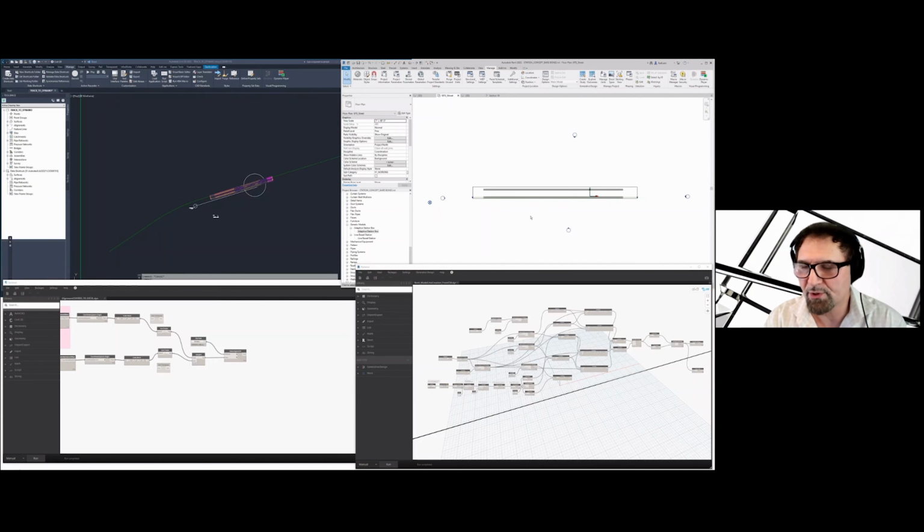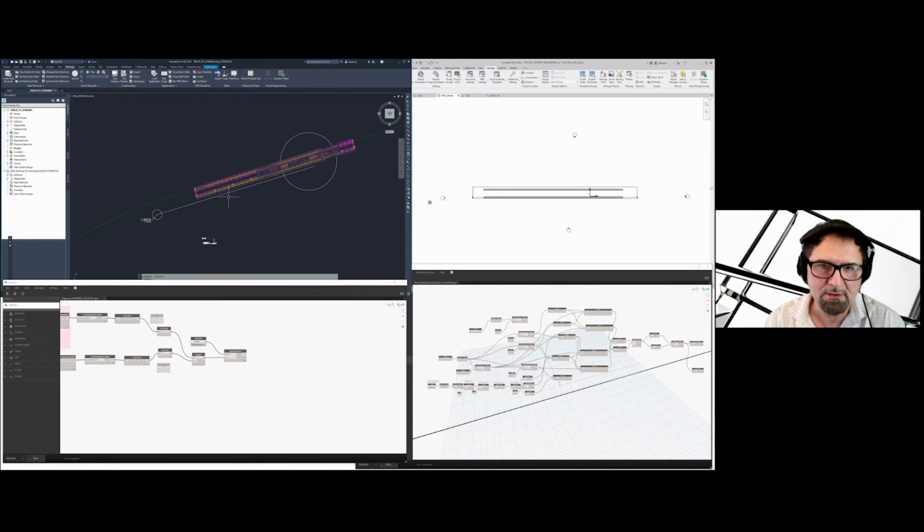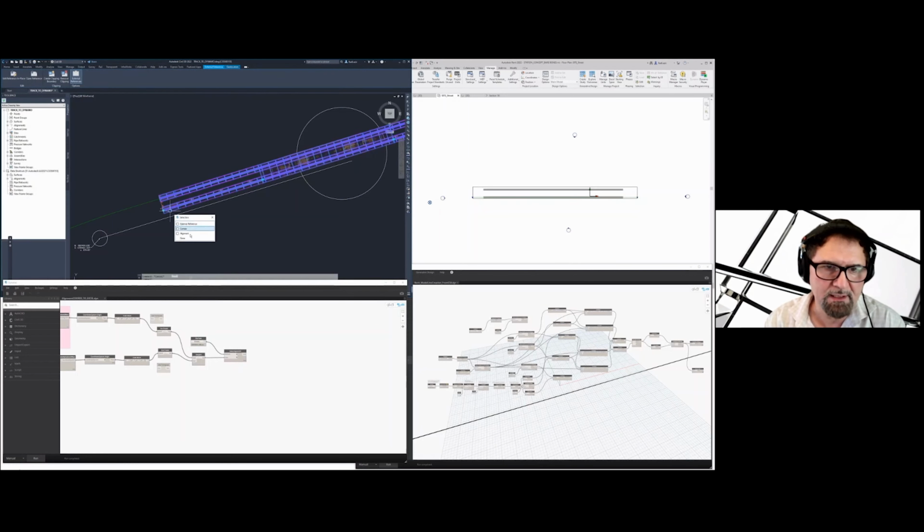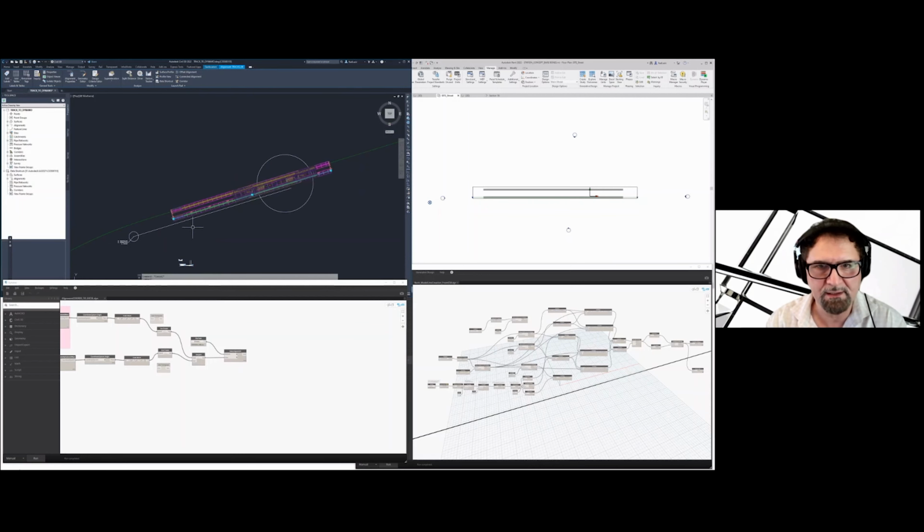And so what happens is if I go here to Civil 3D, select my alignment that is covering that tunnel from start to finish, the station box. And let's say you need to change for whatever reason. Let's say maybe change the direction. I'm going to do something dramatic, so it's going to be very obvious.